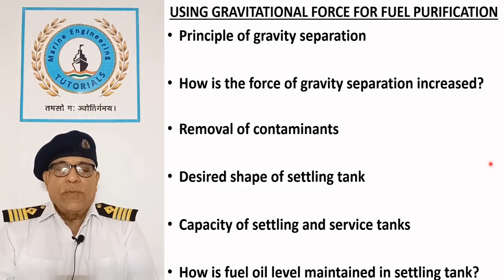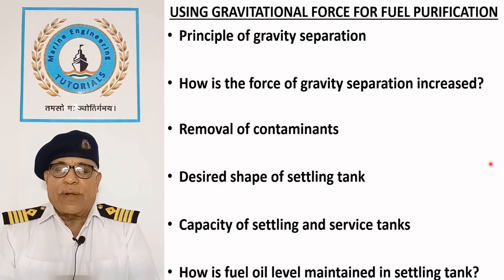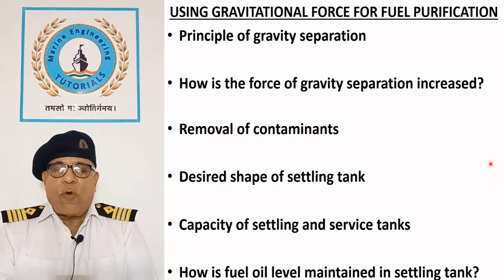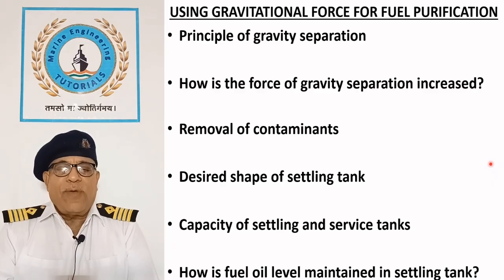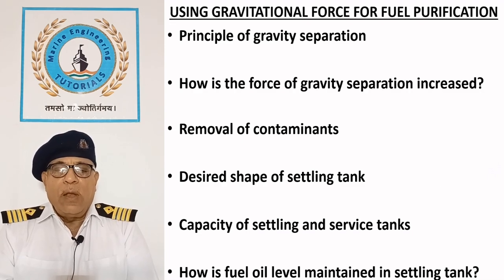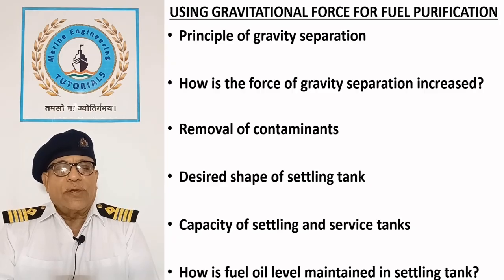The settling tank is also equipped with a low and high level alarm to warn the duty engineer. An overflow pipe is provided to prevent spillage of oil in case of malfunction of automation. On modern ships, purified oil from the service tank overflows back to the settling tank.